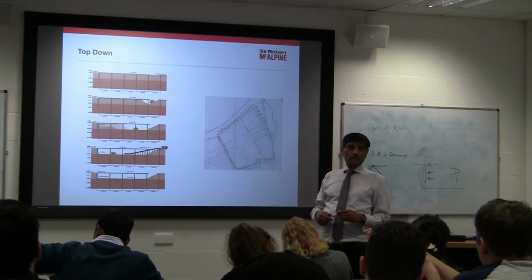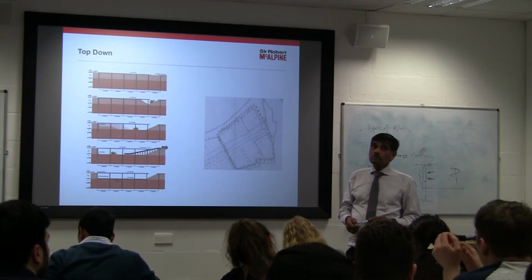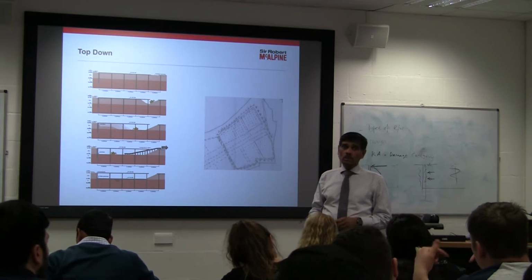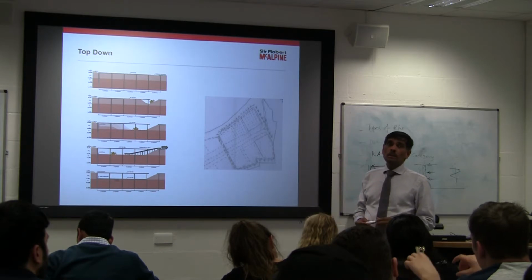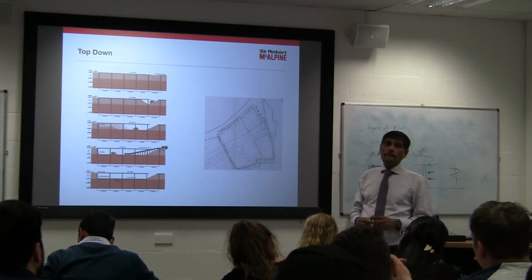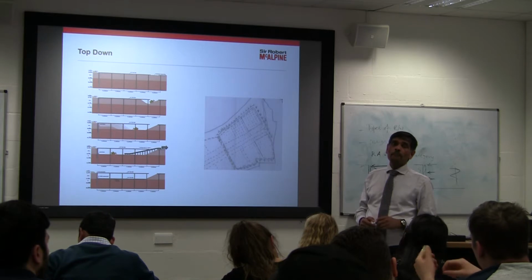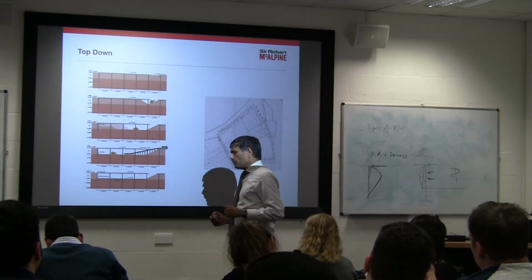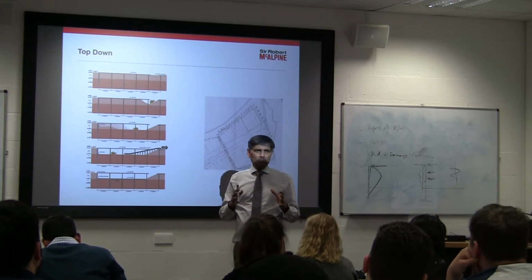There are long excavators. From the start, you put the pile down, but you put the pile cage in. The couplers that go down to the second level below, how do you make sure that they're at the right level, so that when you do break them out, how do you find the coupler to the next slab? Yeah. What we use is something called a template.